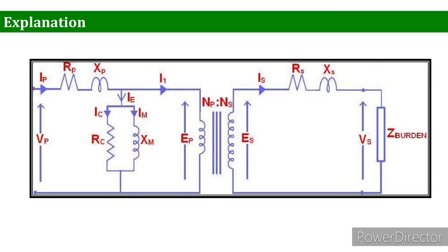The equivalent circuit of the current transformer is similar to the ordinary power transformer, but there are some problems in this equivalent circuit. Basically, the exciting current is not being transformed and is therefore the cause of the transformer errors.